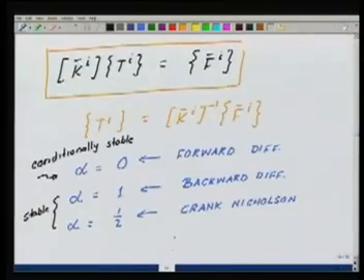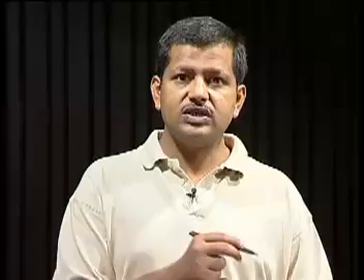In the K hat matrix, I am going to force the first diagonal term to be 1, all other terms in the first row to be equal to 0, and then I will modify the load vector in such a way that the first load vector entry becomes equal to T1 at time Ti, and all other load vector entries are suitably modified.